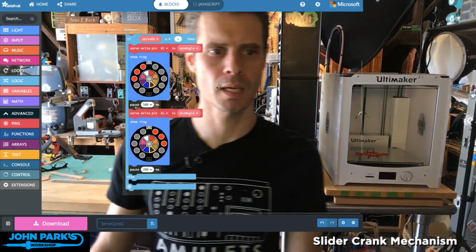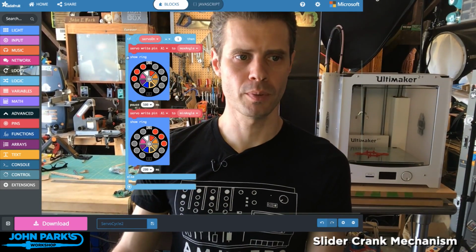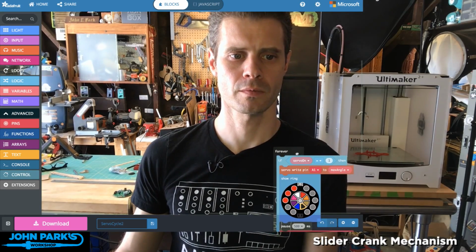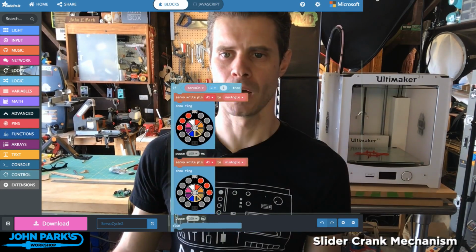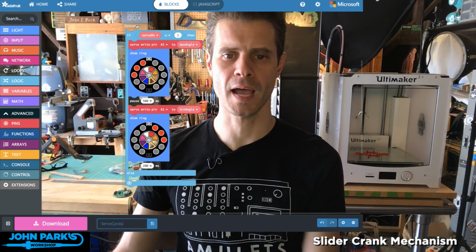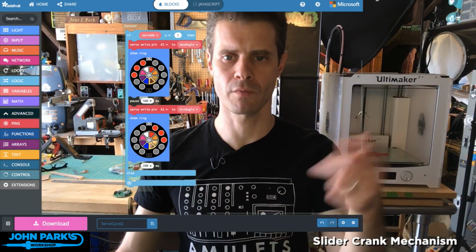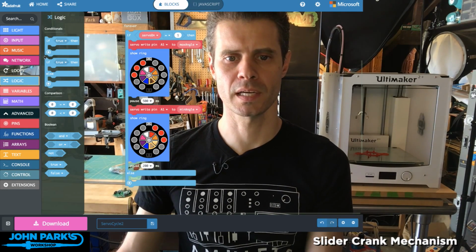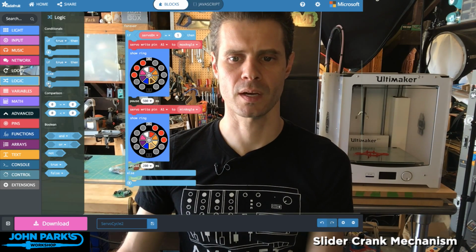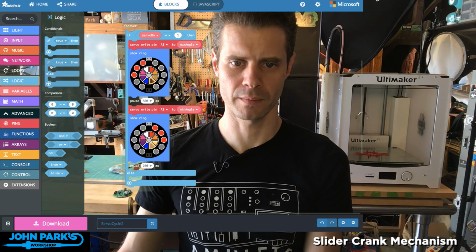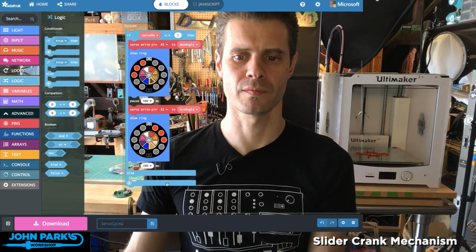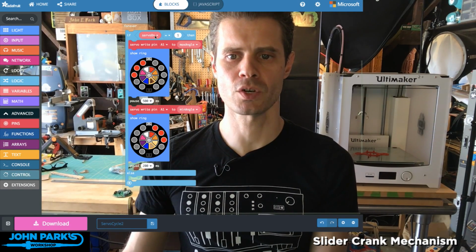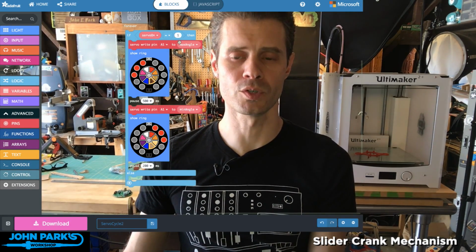What happens in the forever loop, which you can only see that word forever. I'm going to put it on my shirt. Forever. There. This forever loop is what happens all the time. Every tick of the program it runs through, and it's going to use this logic called an if-else statement. Actually, this one is only doing an if. It's doing nothing if the condition isn't met. And the condition I'm looking to meet is, is the servo on variable set to or equal to 1?